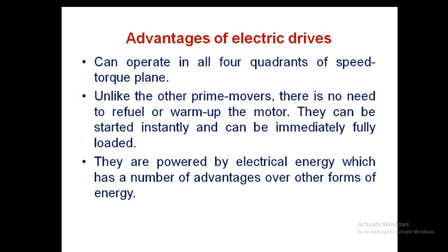Unlike the other prime movers, there is no need to refuel or warm up the motor. They can be started instantly and can be immediately fully loaded, unlike a diesel drive. To start the diesel drive, it requires some minutes of time. But electric drives do not require that starting time. They can immediately go to fully loaded compared to diesel drives.